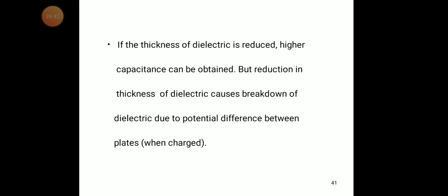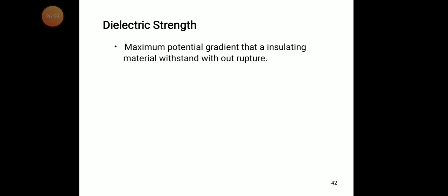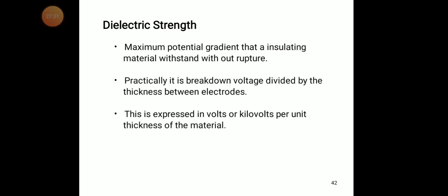So that's why we need a moderate thickness of the dielectric. If you reduce it, higher capacitance can be obtained, but this reduction causes the breakdown of the dielectric. So in order to avoid that, we need to choose a moderate dielectric.